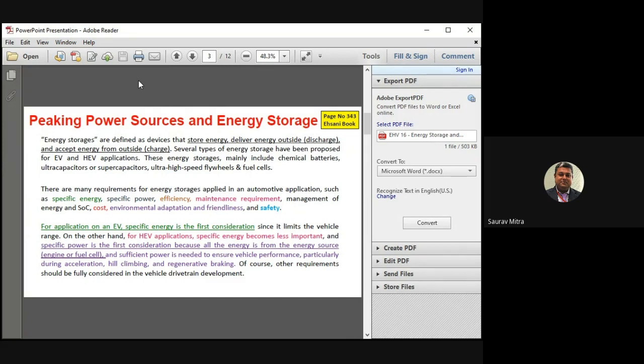Number 1 is direct charging of the battery. Second case is the primary source charging the secondary source. Secondary source is the battery. Primary source can be petrol or diesel. And third thing, which is very important, is called regenerative braking. Whenever the vehicle is going down, the output motor acts as an input generator, and that feeds the power back, charging the battery.